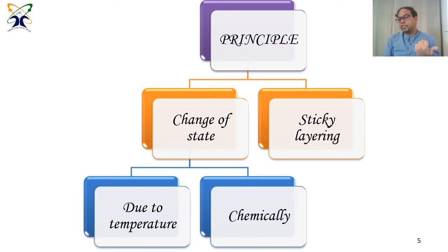The second thing is the change of state. If this material or layer which we want to use for printing changes its state from liquid to solid, from powder to solid, or in this manner, then basically we can print it. For example, as I told you, the hot wax is liquid. If you pour it, it will be liquid, but as soon as it falls down, it solidifies due to its solidification temperature. So basically, if it changes the state, then yes, of course, if these two things are there, then we can 3D print any object using that sort of material.